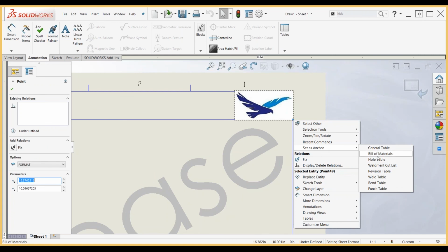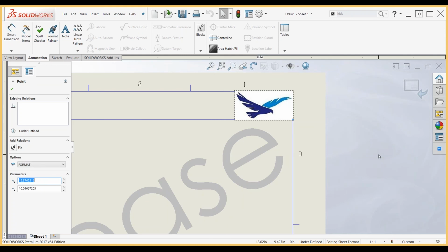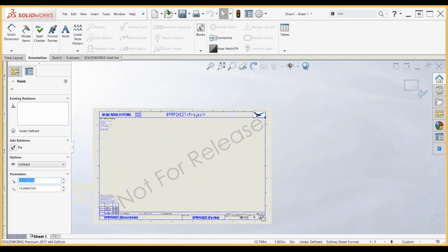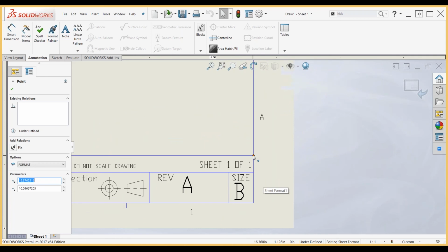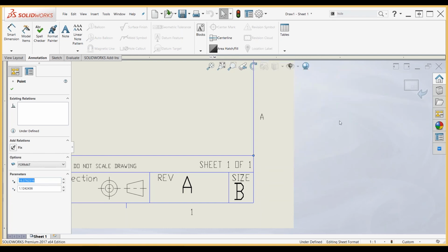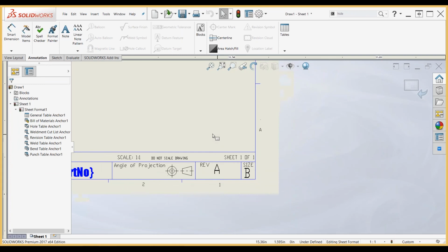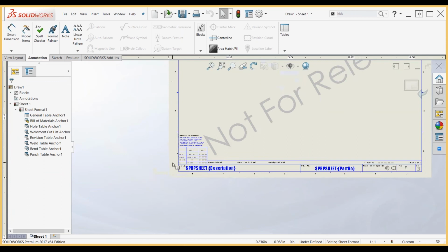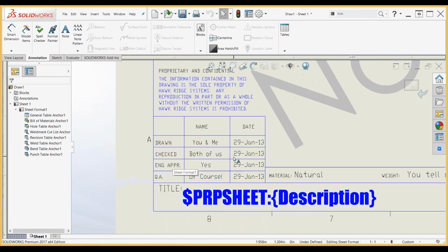So I'm going to select all of these notes here. The order of them is important because you can use Tab to toggle through all of your title block fields. And you can also leave a tooltip. So maybe for the date, I can show an example of the formatting. Or maybe for the name, I want to show a capital letter for the first name and full last name or something. So I can leave all those tooltips to hopefully make it really easy to standardize my formatting. So I've made that title block.